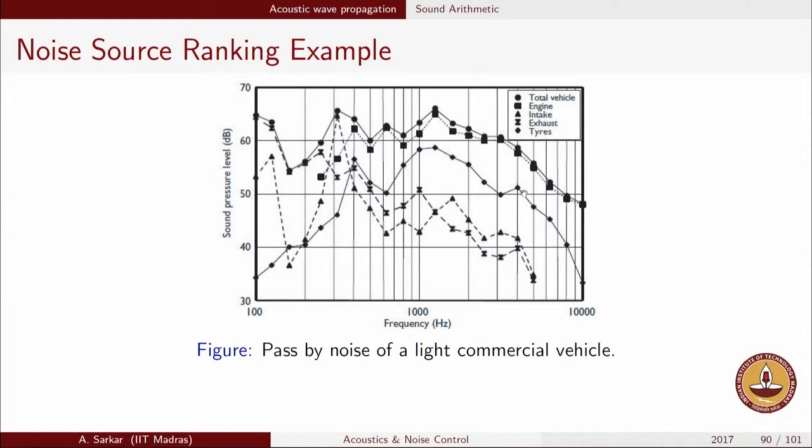So, the noise reading that was obtained when the engine was shrouded properly with an acoustic absorber, in that reading the effect of engine noise would possibly have been struck off, and as a result that measurement will include all noise other than the engine.